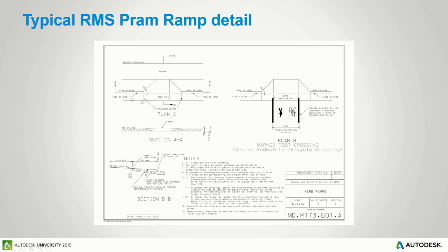So we're going to look at this top left corner here. So effectively our region is going to start about here and finish about here. And we're going to transition up at a nominated offset or a nominated distance, which we're going to let the user configure as well. Then we're going to provide a full width for X amount of distance and then transition it back in at the other end. And it's going to be all dynamic. It's going to be all built as part of the corridor.